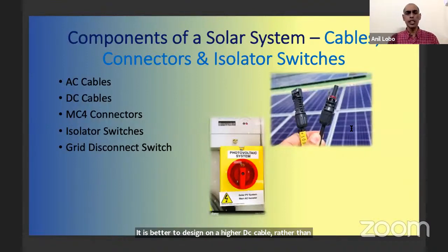Most AC cables, especially in the domestic circuit, will be no more than 4 mm. 2.5 typically, and you can go as low as 1.5 without affecting the integrity of your system. But if you go wrong with your DC cable, not only will they overheat, there is a safety aspect of catching fire. The next thing which is often ignored are the MC4 connectors.